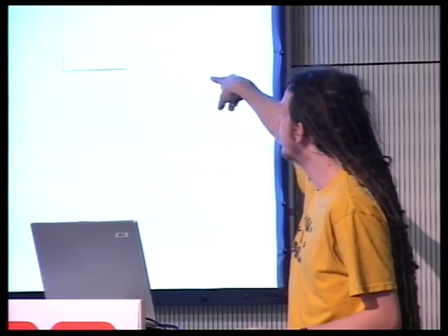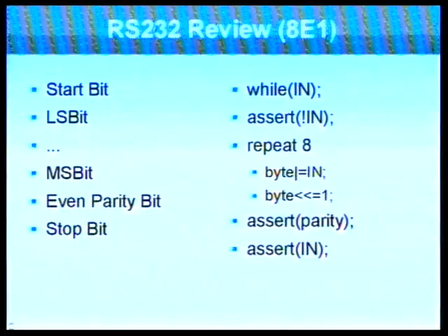To send 0x90, again, we have the less significant bits, followed by the 1, and then we have the most significant bit. That's the 8th bit in the 9 nibble. But here the parity bit is 0. If you look at these enough, it's easy to recognize the difference in a scope recording.